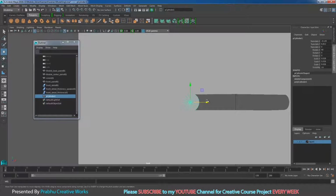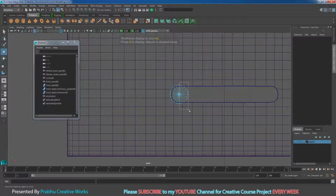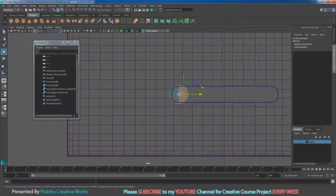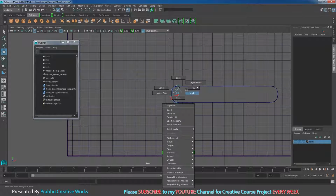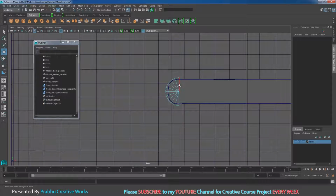Go to front view, press 4 on the keyboard. So right click and choose face. So select this one half face and press delete on the keyboard. Right click and choose object mode. So right click and choose edge. Select this edge. Shift select this edge.